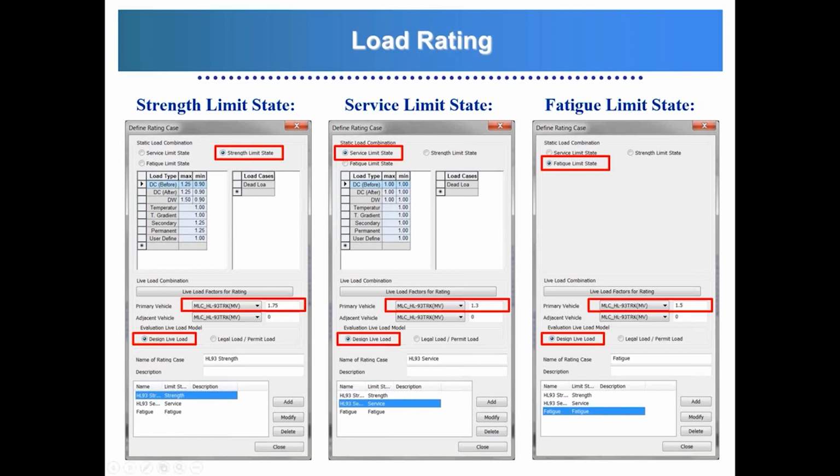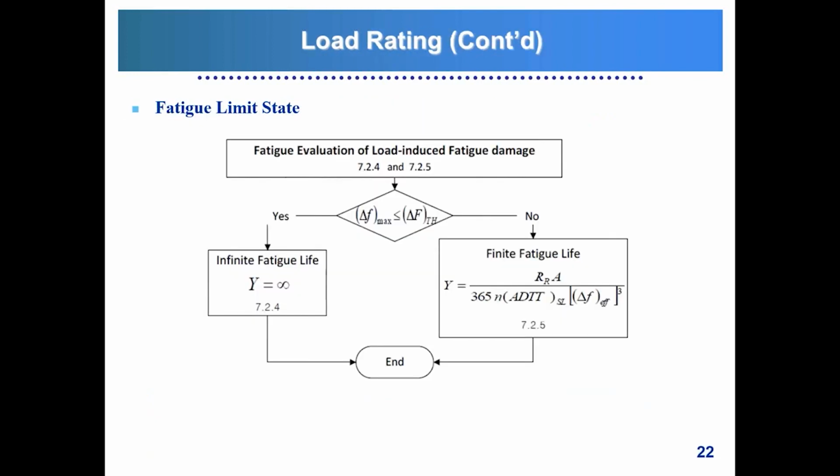If for some reason you need to use different load factors, you also have the option to modify these factors. Now, I will not go into too much detail for the strength and service limit states, because those are more commonly covered. I will go a little bit further into how MIDAS calculates the fatigue rating, and what the typical results look like.